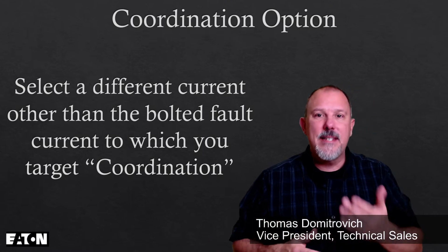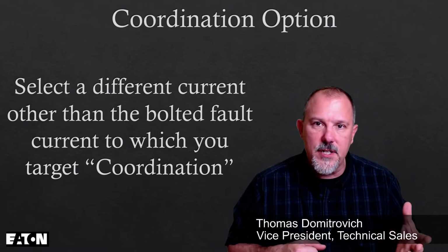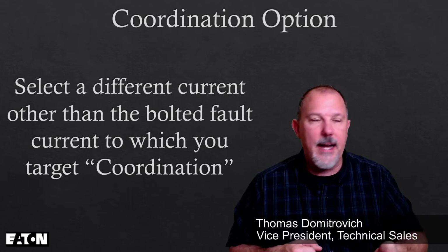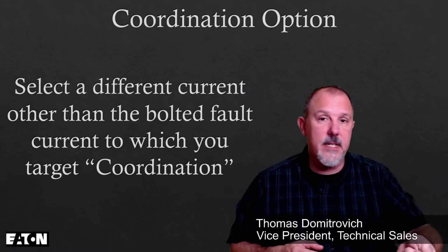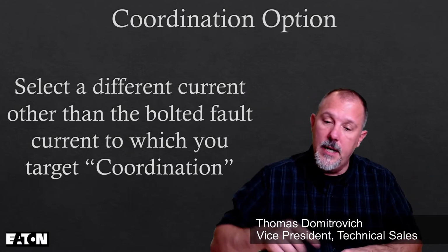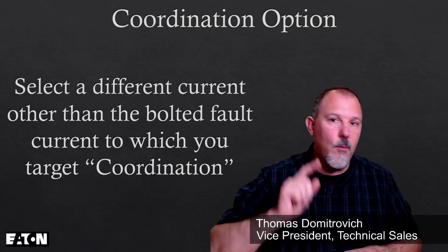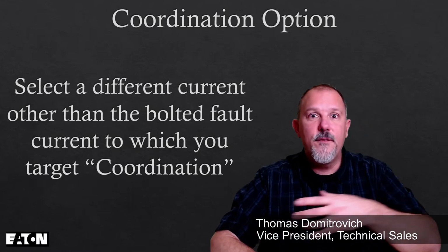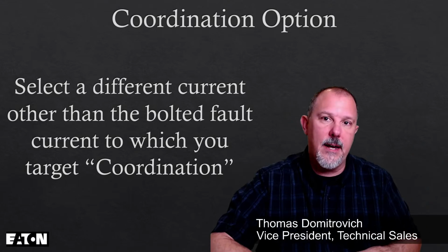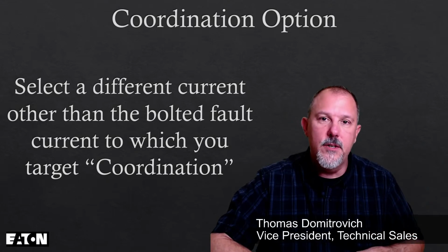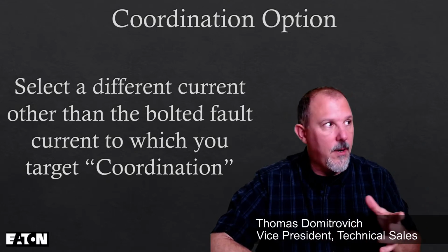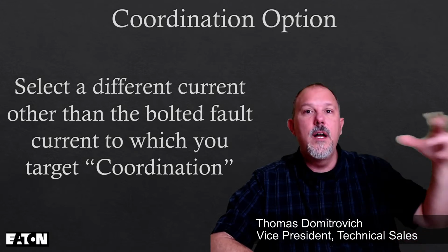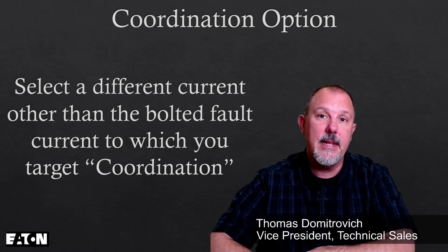I look at my receptacles on the outside of my house. I got frustrated one day. I went outside to do some work. I plugged my extension cord in. Nothing worked. I tried to hit the reset button. It would not reset. Every one of my receptacles on the outside of the house, none of them worked. So I had to replace them all. I replaced them with a standard receptacle. I have a GFCI breaker inside the house.